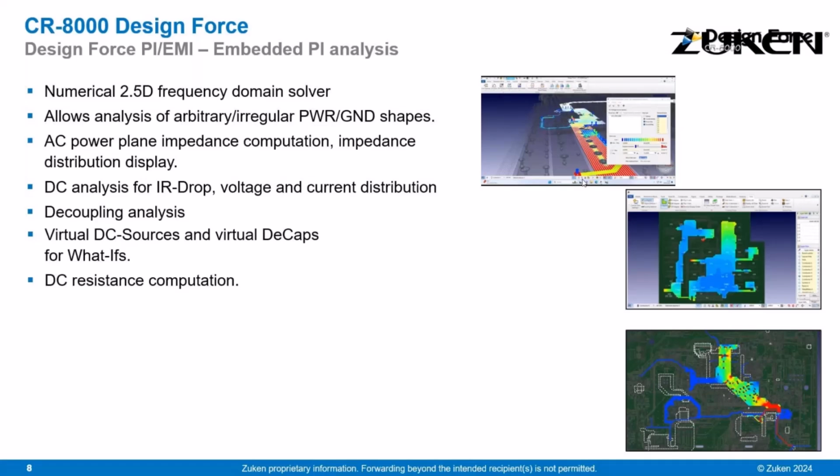There's also decoupling analysis, which evaluates the performance of decoupling capacitors. Virtual DC sources and virtual decoupling capacitors can also be used for what-if scenarios, so we can test changes before implementing them physically. And finally, it computes DC resistance, giving a complete picture of the board's electrical performance.